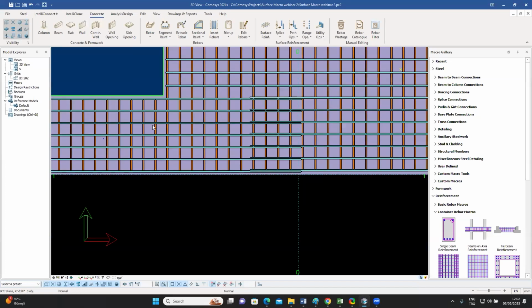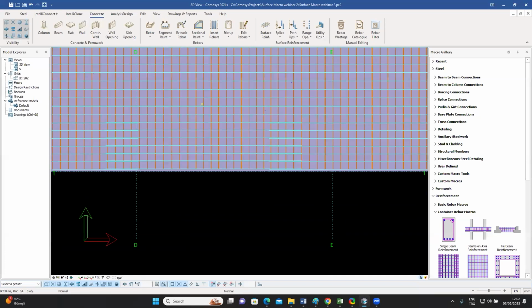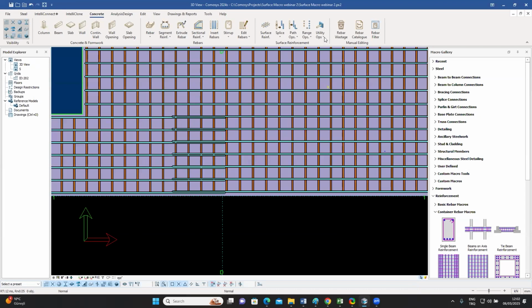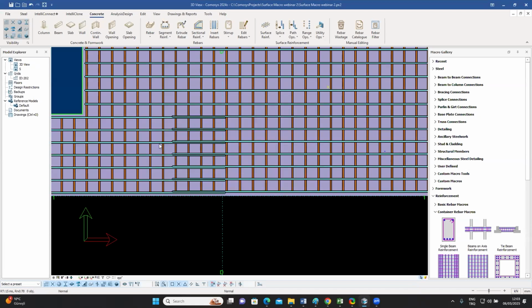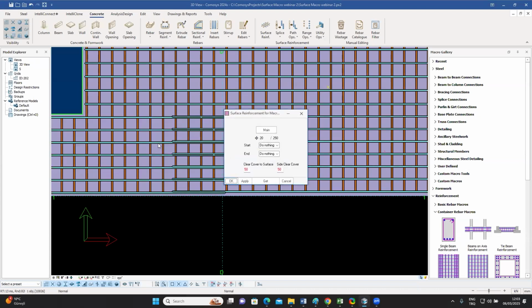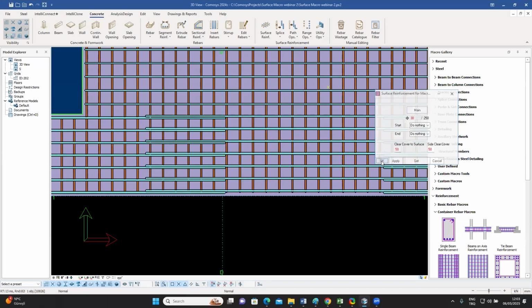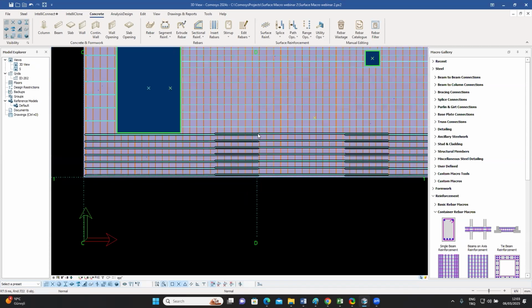My settings are at the moment at 6 meters. You can change that to 12. It's 6 meters, then another 6 meters, the second splice. And if you see, this length has been calculated automatically, and if I go in and list my operations on that rebar, it's 50 feet. So if I were to go to my original surface macro and change the diameter from 20 to something else, 30, for example, you will see that the splice length will also be recalculated automatically at both points.